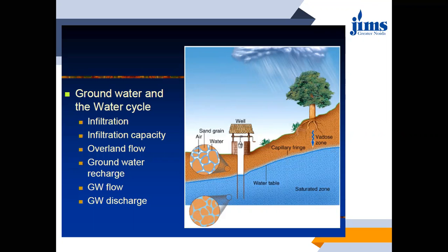Okay, so this causes what? This causes the groundwater recharge. Then another influencing factor over there is the groundwater flow. See, apart from percolation, what if the water percolates into the ground surface and it doesn't flow up to the water table? Then what will happen? A perched aquifer will be formed. Water will move somewhere, it will be entrapped somewhere, and pockets will be formed, and therefore perched aquifers will be formed.